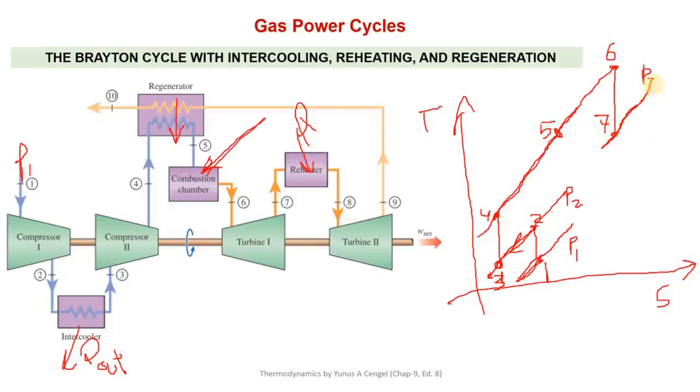So from point 7 till some point 8, for example, point 8 is at temperature T8 equal to T6, but during this process heat is supplied at constant pressure. So it reaches the same temperature again as at point 6, but during this process specific volume is further increased.